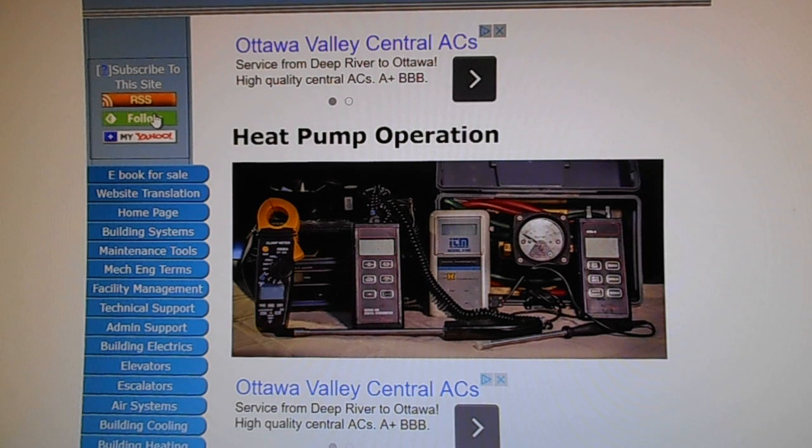The heating cycle reversing valve allows for the direction of flow of the refrigerant to be changed or reversed upon demand, allowing heat to move in either direction of the 2-stage heat pump. The evaporator in effect becomes a condenser coil and adds heat to the air that the supply fan is moving through it. The condenser in effect becomes the evaporator coil. The supply air fan blows cold air across the evaporator coil, which is now effectively the condenser coil, and supplies warm air to the conditioned space.